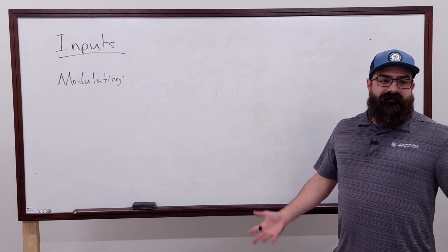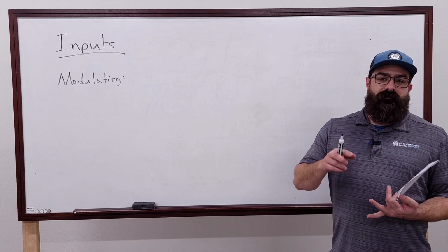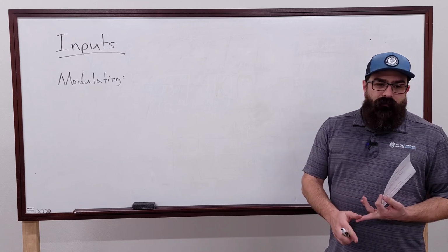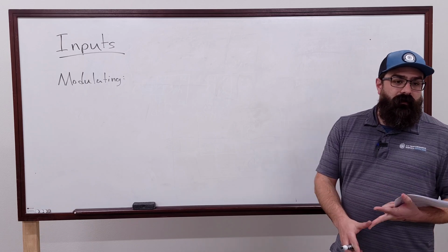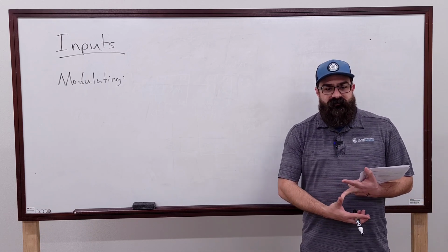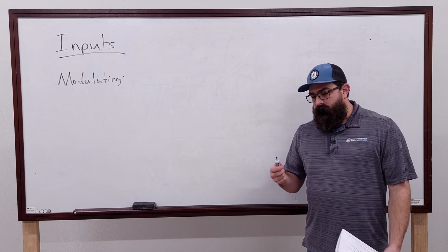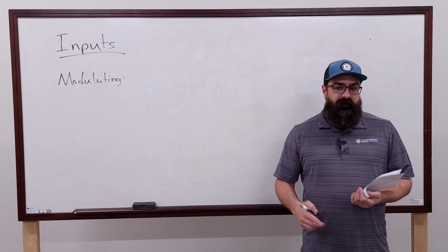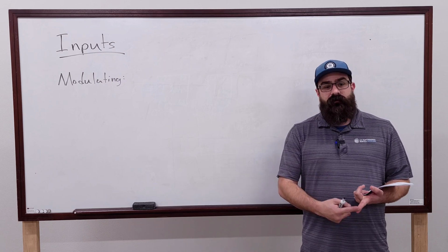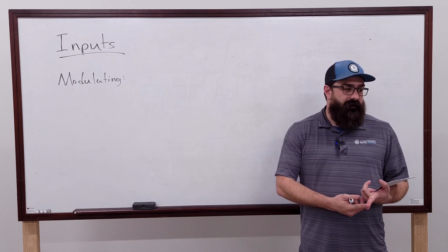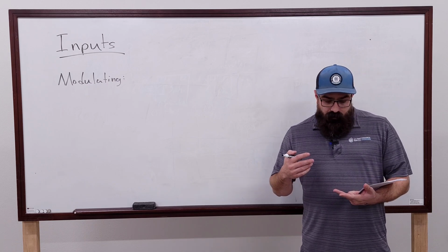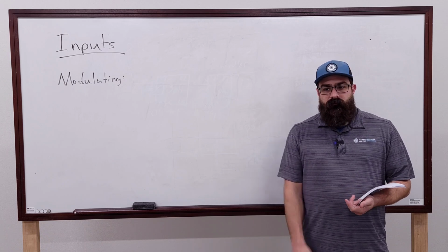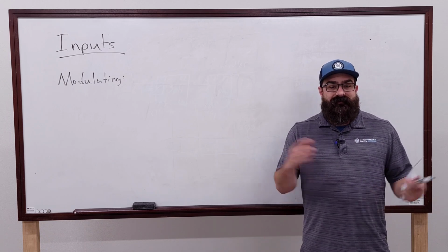So anything that can be scaled, a resistance, a pressure, an output, like a 0 to 100% value type situation. Damper actuator, a chill water valve, a hot water valve, a pressure transducer on a line set monitoring high pressure, low pressure, static pressure in a ductwork, pretty much anything that is scaled.